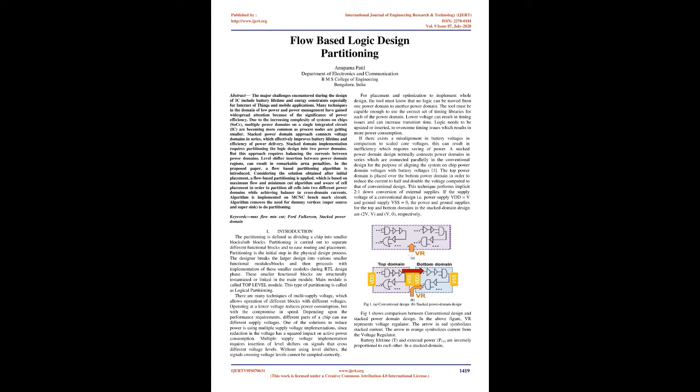For placement and optimization to implement whole design, the tool must know that no logic can be moved from one power domain to another power domain. The tool must be capable enough to use the correct set of timing libraries for each of the power domain. Lower voltage can result in timing issues and can increase transition time. Logic needs to be upsized or inserted, to overcome timing issues which results in more power consumption.